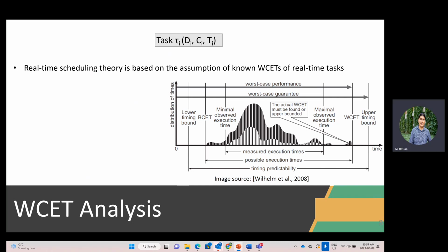No matter the input, the temperature, the variability, the environment, or even what other tasks are running with me, my worst case execution time is 2 milliseconds. Hence, does this meet my 10 millisecond control loop, or 10 hertz control loop, requirement or not? If it meets it, great. If not, then I need to redesign something, either the hardware or the software.